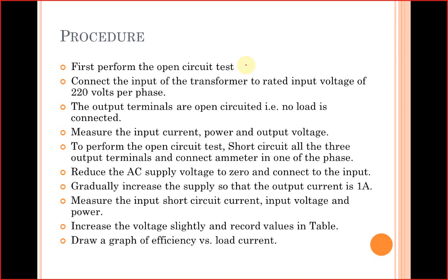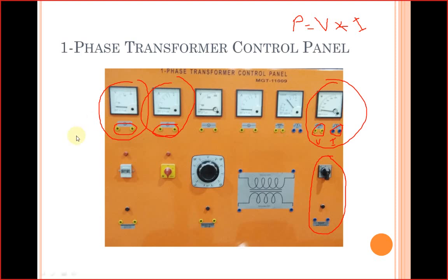Okay, the other question is, sir, why we don't use a multimeter instead of all these meters? Yes, we can, and we will use a multimeter. If you are using a digital multimeter, you can use it for voltage, current, resistance, capacitance, and frequency.